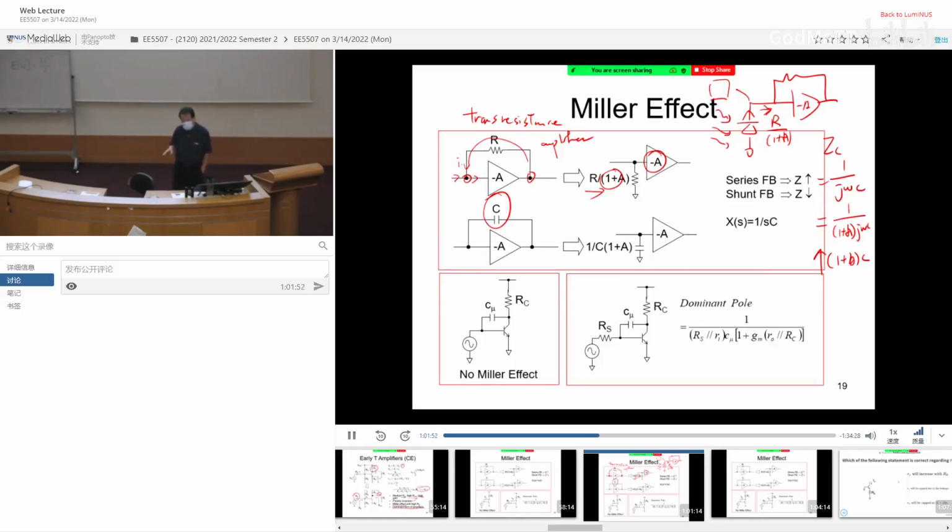So that is what makes it infamous. A lot of the time, capacitance determines the frequency response. If you want to go to high frequency, you want the capacitance to be as small as possible. Agree? Larger capacitance doesn't give you high frequency response. It limits the bandwidth. So this Miller effect makes the capacitance worse and therefore causes the equivalent dominant pole to be smaller and limits the bandwidth. That is what makes it infamous. Having said that, it's not all bad.